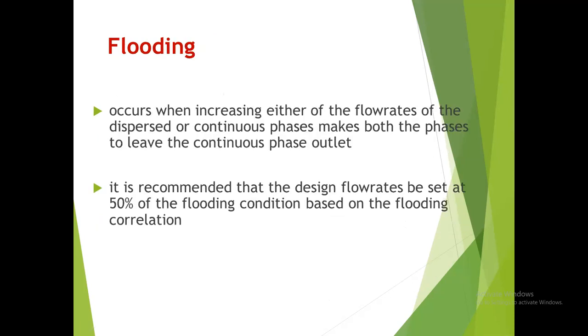Now, in the design of our extraction tower, you were shown already how to determine the amounts of the extract and the raffinate layers, how to determine the composition. Now we go to the design of your extraction tower. The basis of how big your extraction tower should be is on the flooding condition. When is the tower flooded? So you determine that particular condition when the tower is flooded, and then you're just simply going to lower down the corresponding flow rate. That way, it will not be flooded anymore.